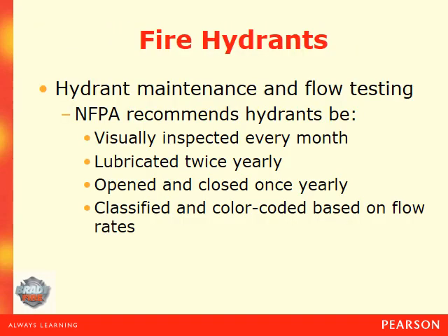Hydrant maintenance and flow testing needs to be done either by the fire department or the water department or a third agency. And according to NFPA, they should be visually inspected every month. They should be lubricated twice yearly, and that should be with some sort of food grade type oil. And what they want lubricated is the bonnet on top and the couplings on the side. You should open and close the valve yearly, and they should be classified in terms of color coded based on their flow rates.